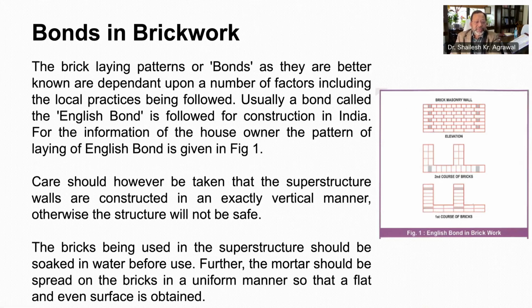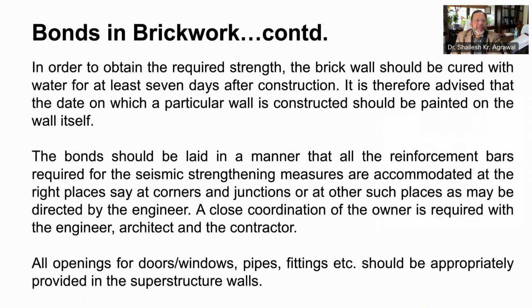Care should also be taken that superstructure walls are constructed exactly vertical, otherwise the structure will not be safe. Also remember, bricks before using should be soaked in water, and mortar should be spread on brick in a uniform manner. Once the bricks are laid, they should be cured with water for at least 7 days after construction. Also, sometimes for seismic requirements, reinforcement bars are to be provided at corner junctions and other places, and therefore bond should be laid in a manner that all strengthening measures are well accommodated.